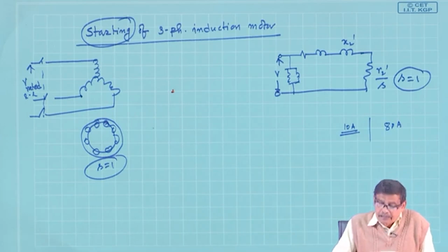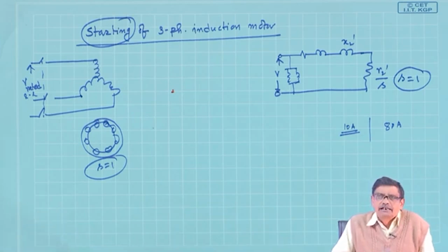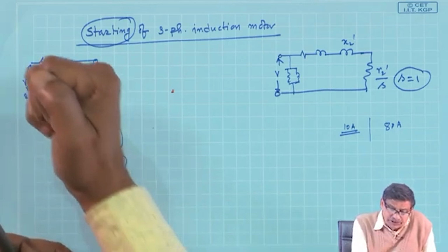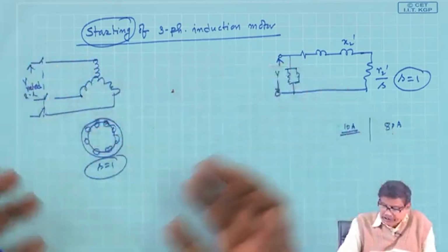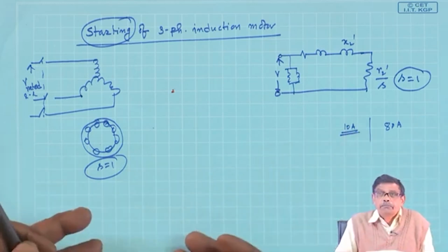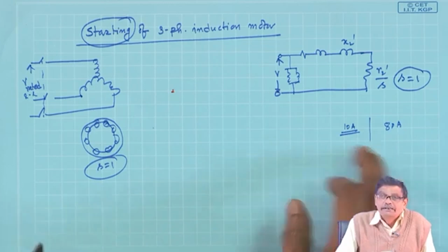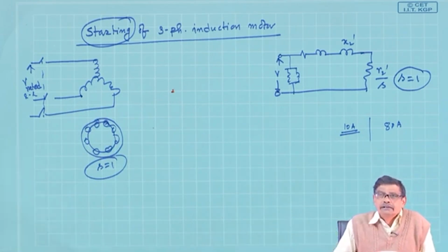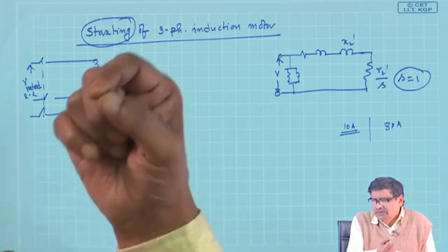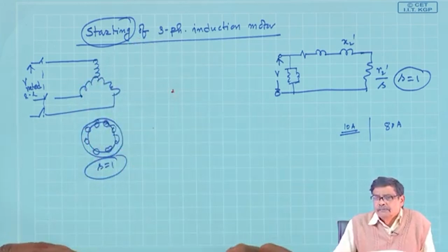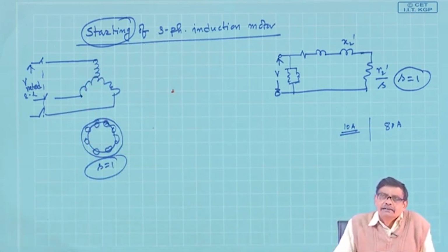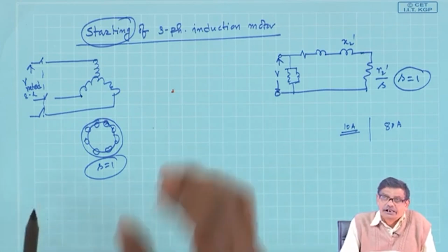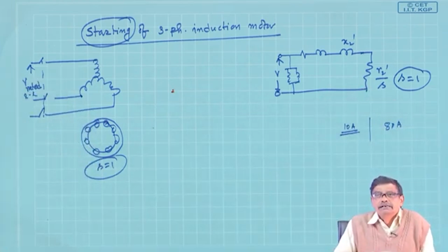if I pass it? See, there is a tricky thing. If the motor is a very small size motor, then you switch on the supply at full voltage, starting torque will be there, inertia is less, and the machine will pick up speed very fast. It will take 80 ampere, but for a very brief period, and you know that to spoil a winding you require large current for considerable time. I square RT decides the amount of heat generated. Therefore, you should not be too skeptic.